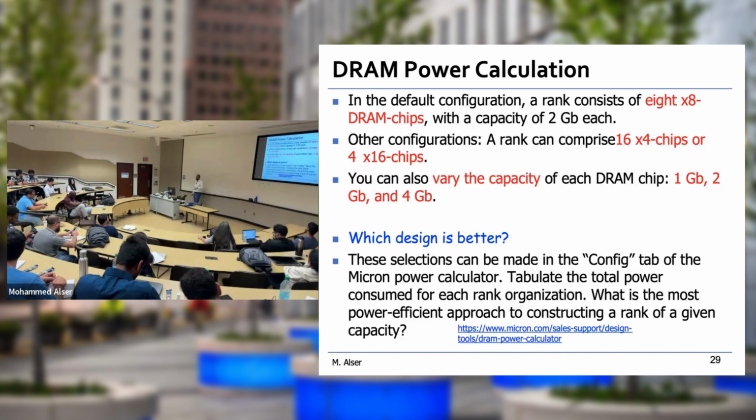So the interface is standard, right? But the parameters you send are really different. For example, we talked about refresh rate. Who's doing the refresh? The memory controller. If I need to do it faster, then the memory controller should send more requests, right?